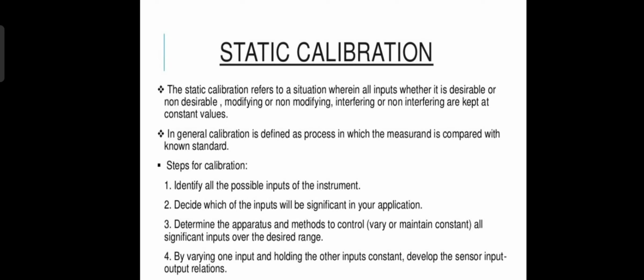The transducer calibration is carried out under the assumption that the wiring and the signal conditioning will function as designed, but one bad connection invalidates the data. Hence, it is not recommended to depend solely on the transducer calibration.